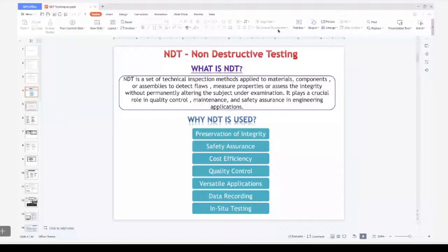So what are the matrix related defects, fiber related defects? Then there is an interface between the matrix and the fiber. Then in the process, especially with the resin, when it cures there are some void formations. Then during curing there are manufacturing related defects like contaminations, inclusions, and so on.